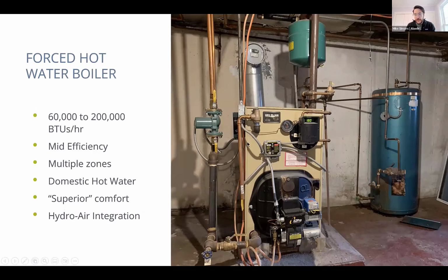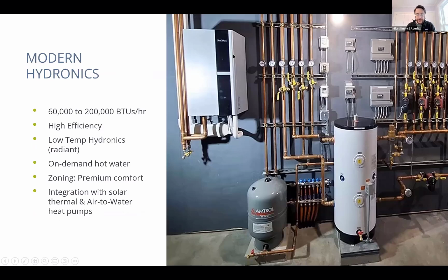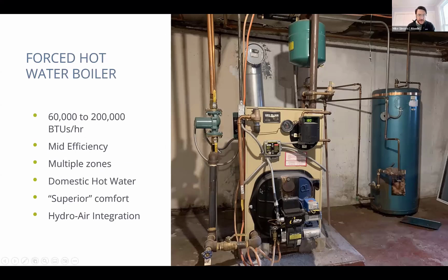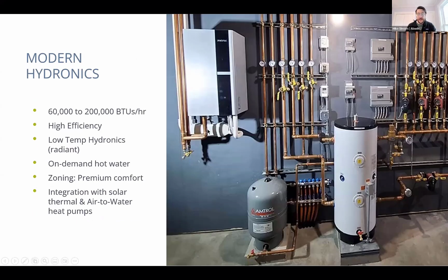With traditional boilers, another thing that we didn't talk about with the high efficiency boilers, like any of the high efficiency equipment, the expected lifespan of it is like 15 years. Same thing with the heat pump. We should be setting expectations about 15 years. With the older equipment, the life expectancy of it's closer to 30 years. And the reason for that is this is all just made of like cast iron and steel, and it is a very inefficient heat exchanger. But with the new stuff, it's all like finely machined stainless steel and aluminum, and it's a lot thinner, just physically.